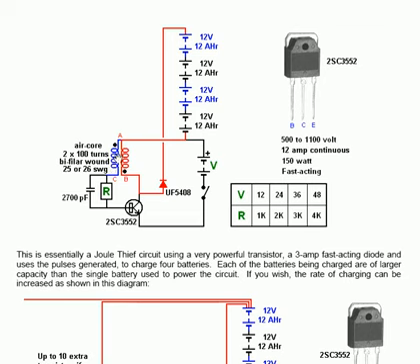The drive battery powers the circuit. He has a 2700 picofarad small ceramic capacitor connected across the resistor. Ostensibly, we'll say for the moment that is to adjust the frequency of the transistor. It's slightly more subtle than that, but we're not going to go into that just here.